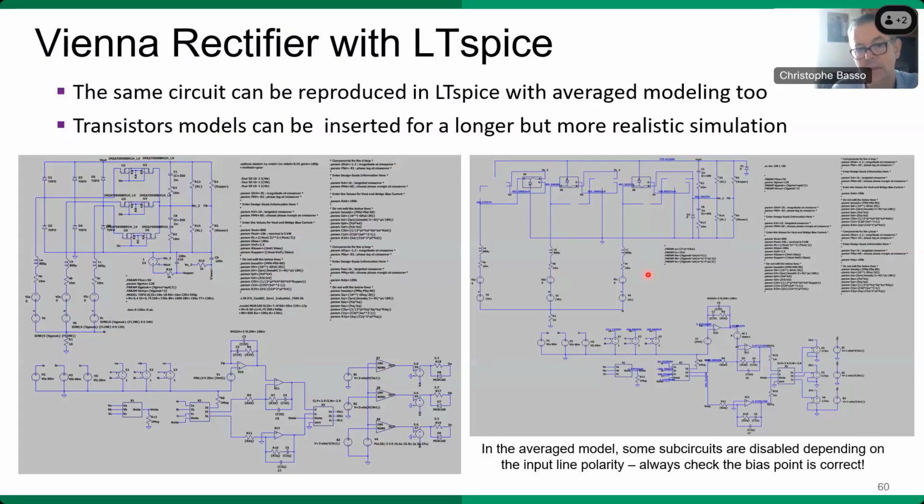It's just because in some cases, some of these diodes here will or will not conduct. And that's why you have one of the active PWM models, where some of these models are active or turned off. And once you do that, then you can extract the small signal response here and run a compensation exercise on the outer voltage loop here.